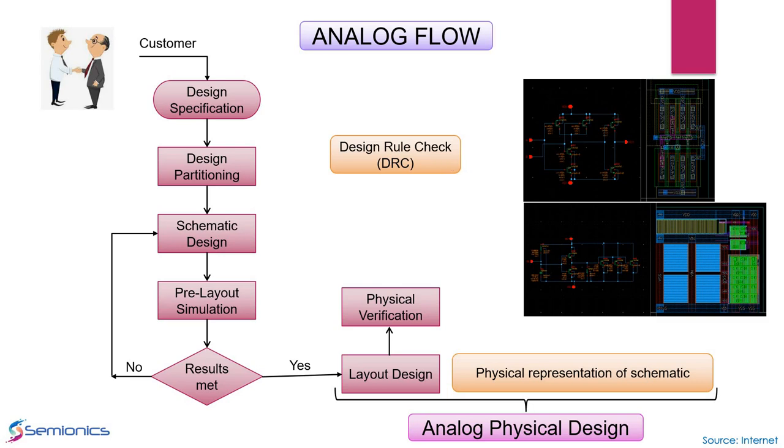Now it's not only the fabrication aspects, but there's another part to it called the layout versus schematic check. This also needs to be done. So what is this? Whatever design the schematic engineer has done needs to match with the layout, or whatever the layout engineer has done in the physical implementation has to exactly match with the schematic. That is what we are trying to verify in the layout versus schematic check, right?